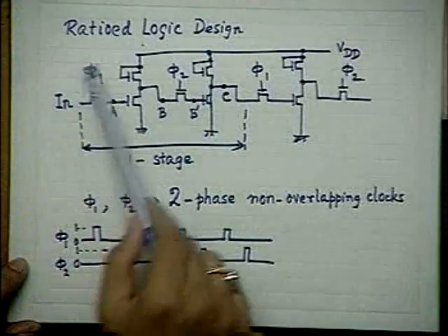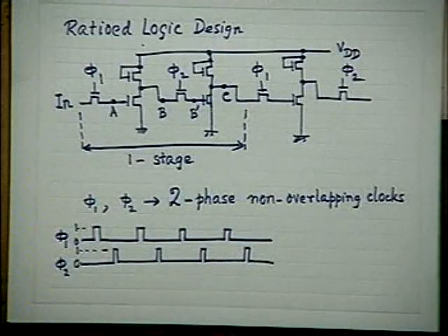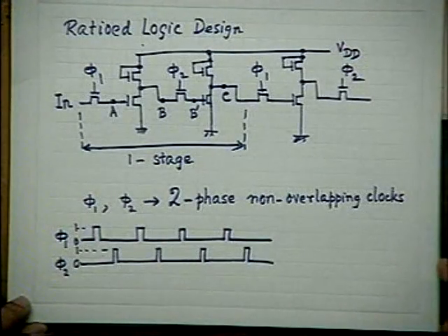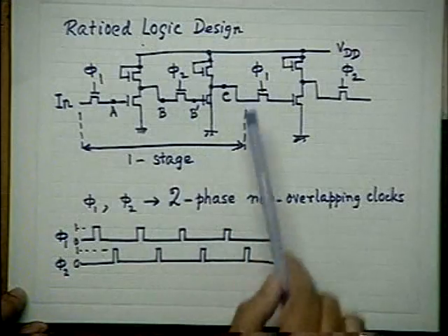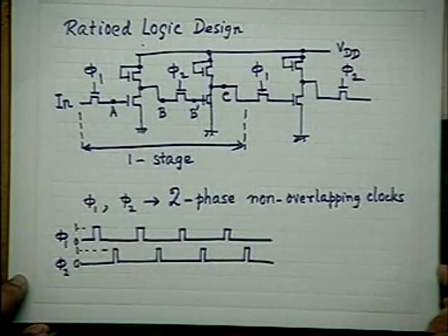You remember that. This forms one half stage. Half stage means either the master or the slave. And if we combine them, the transistor count will be much higher than in this particular case. So that is one benefit. We shall discuss gradually what the benefits are. One benefit already achieved is that the transistor count here is considerably less than in the conventional static case.